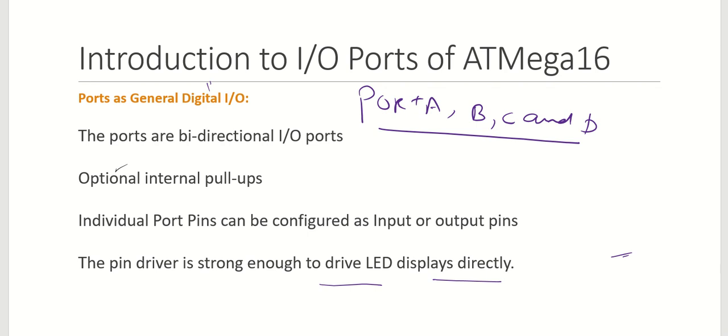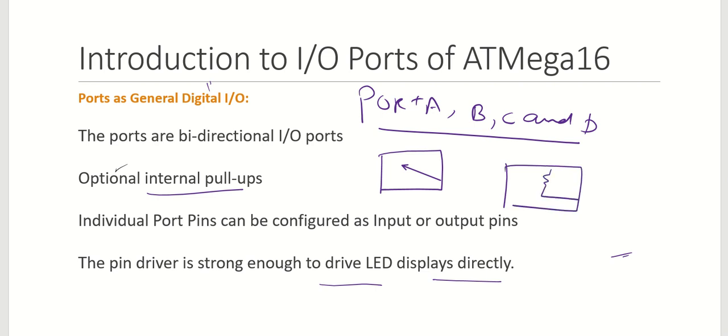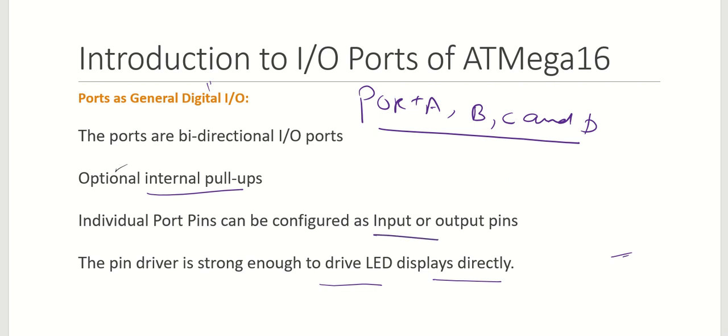We have the option of internal pull-ups. Internal pull-ups are there which can be connected or disconnected to the port pin. Okay, so we have internal pull-ups. They can be enabled or disabled on the port pins. Individual port pins can be configured in input mode or output mode.